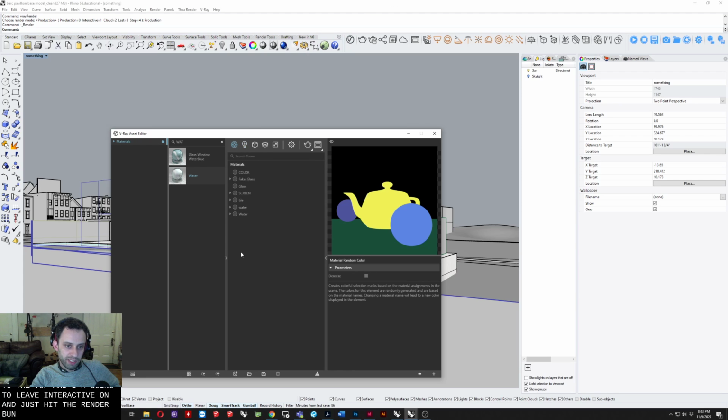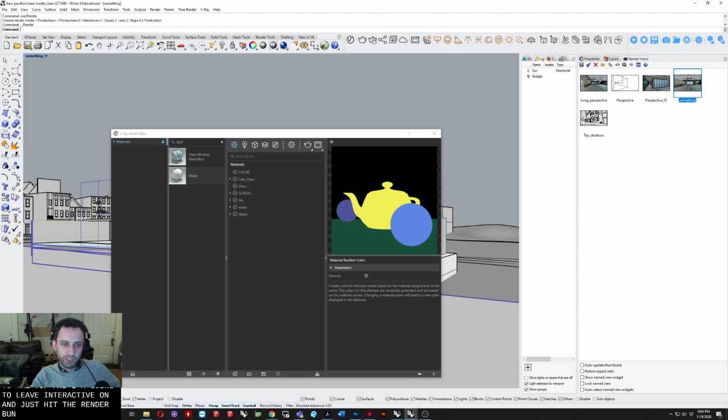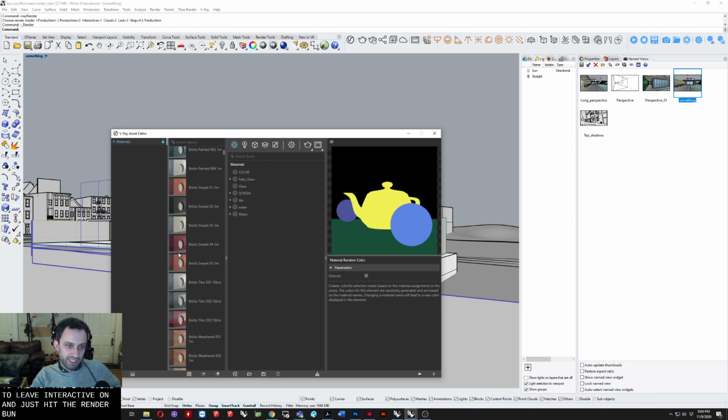Here is mostly your basic materials, setting up for clipping planes, things like that. Good things to keep in mind, always work off a named view. That's going to be huge for you. Make sure you name your textures as you go. As I said, there is a lot of existing textures here. Think of these as a starting point if you use them.